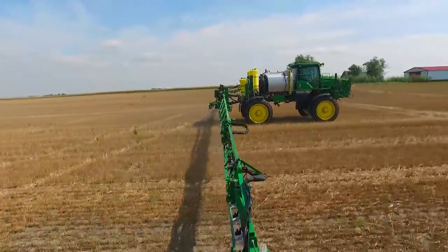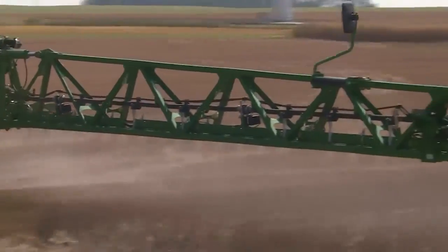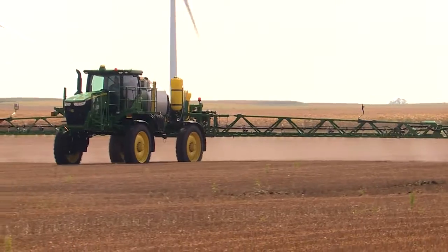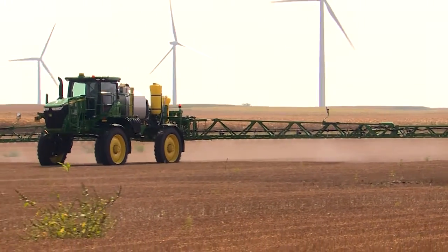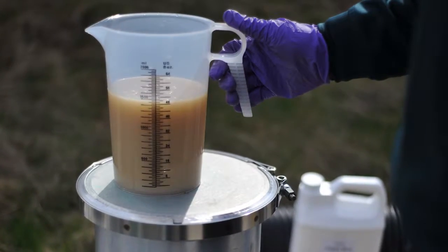They're fairly resistant to the effects of evaporation, but our smaller droplets, as they travel from the nozzle to the target, begin to evaporate. Droplets of a certain size might have left the nozzle large enough to not be driftable, but as evaporation reduces their size as they travel from the nozzle to the target, they get to a point where they are now small enough to be blown off target. Or worse yet, we'll lose them completely. They evaporate completely, and we don't get any of that product containing those droplets down to the target. So adjuvants can help us protect the droplets as they go from the nozzle to the target.